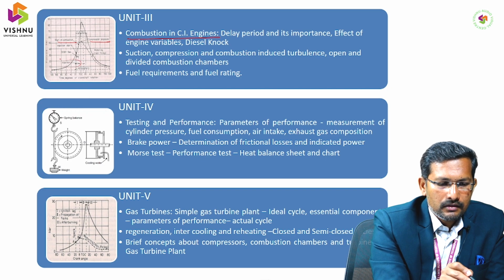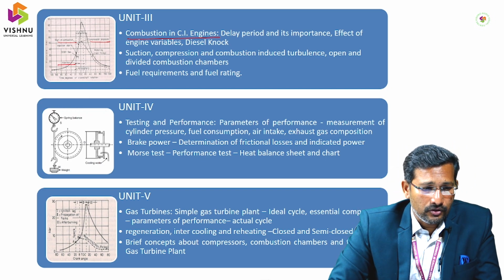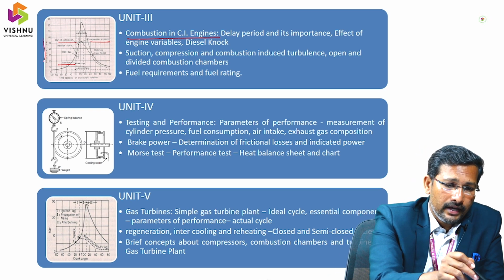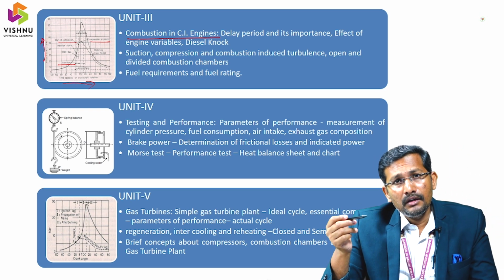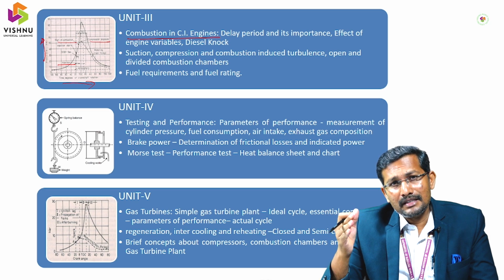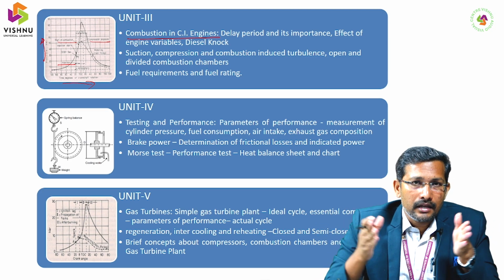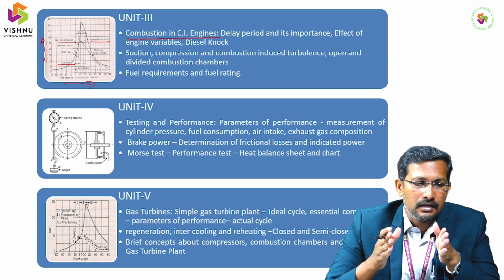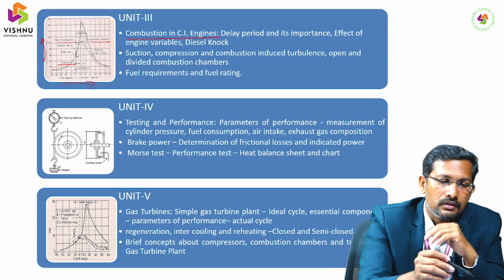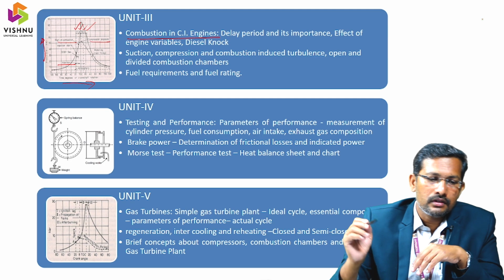The curve is plotted against crankshaft rotation in degrees: on the y-axis we have pressure, on the x-axis crankshaft rotation. Across the suction, compression, expansion and exhaust strokes, if you monitor when fuel injection starts, there are four stages, 1, 2, 3, 4. This is the region.